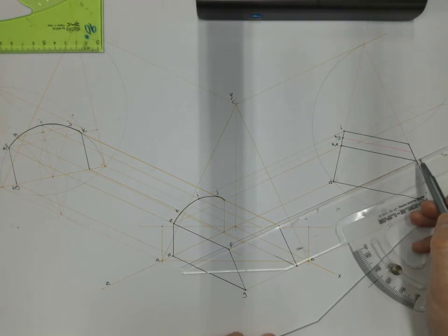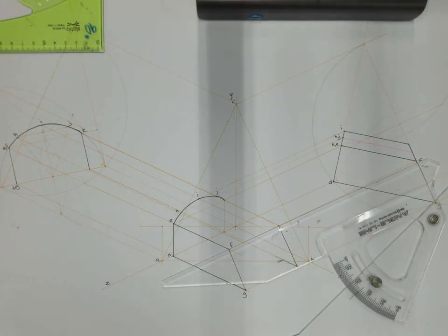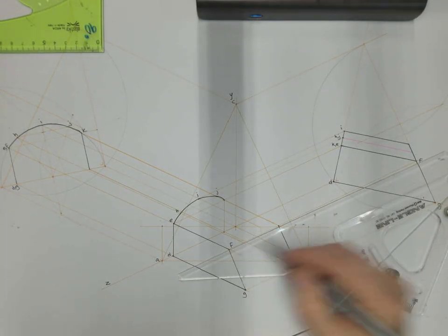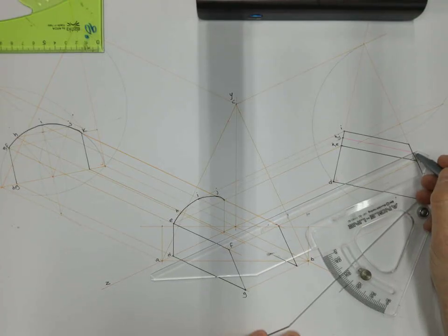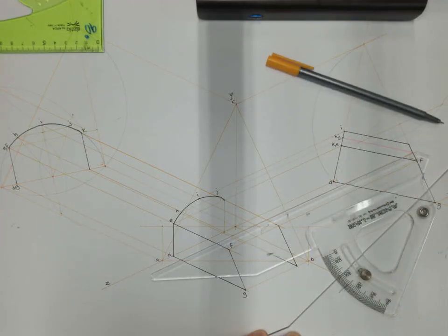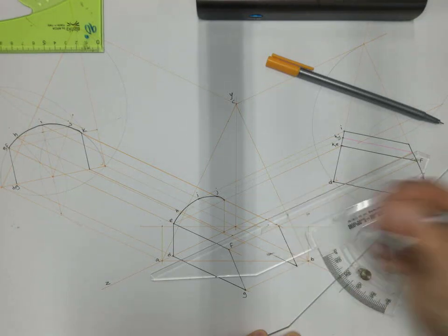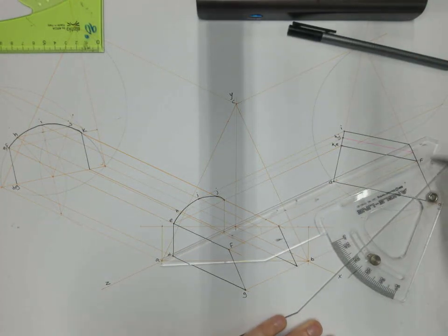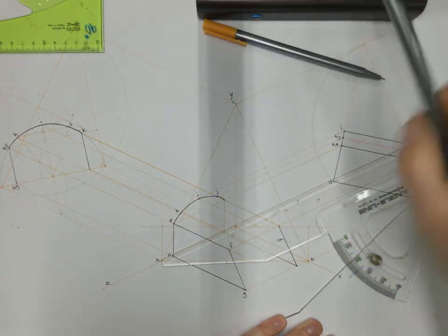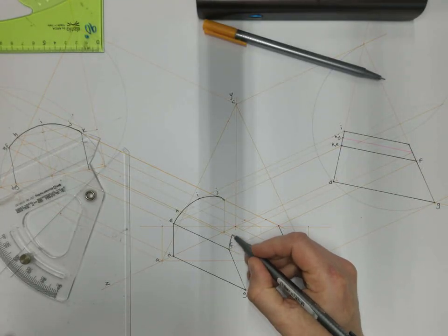So, F, this point here where we've already taken it down parallel to the z-axis, gives me that point and that point. This one, bring it down, gives me that point in line with H and this point in line with J, and then this top point here, bring it down to be in line with I. So there's all the points you need then to finish off.